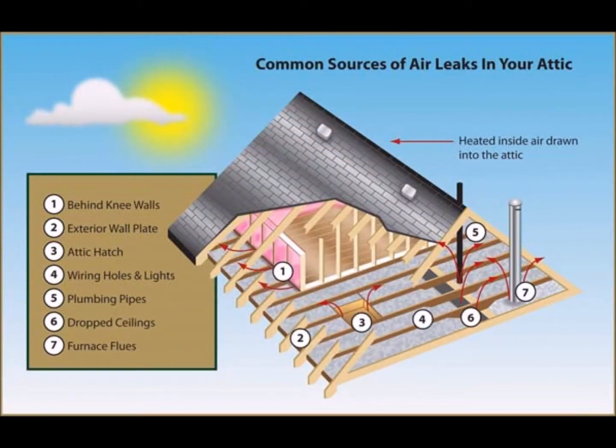If there are cathedral ceilings in the house, the ceiling and penetrations through the ceiling should be carefully sealed to prevent any air leakage. This may also include special air-sealed light fixtures, as well as caulks and sealants at all penetrations and joints, and avoiding leaky ceiling systems such as exposed tongue and groove boards. Leakage of humid indoor air into cold cathedral roof cavities is a major cause of condensation and moisture problems in